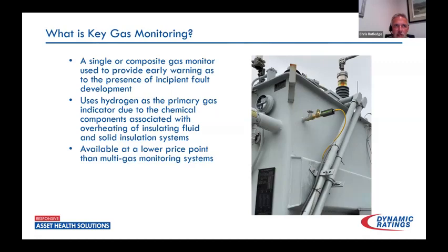So obviously a huge savings, and I think that if we are, and we all are on some type of budget, when cost constraint is a consideration, maybe it should be looked at as to how much coverage can I get with this transformer, outside of just getting oil values. Because I really do feel like the hydrogen will provide you with notification, as well as the multi-gas, that something's occurring. Again, it just doesn't give you that diagnostic ability remotely. You can still go out and take your manual samples and do that.